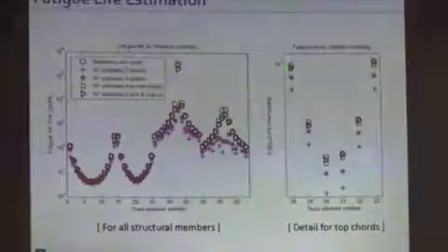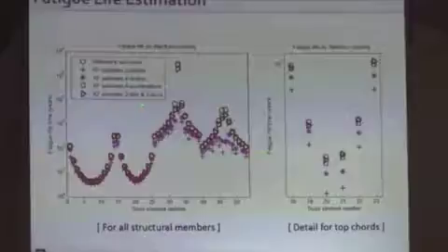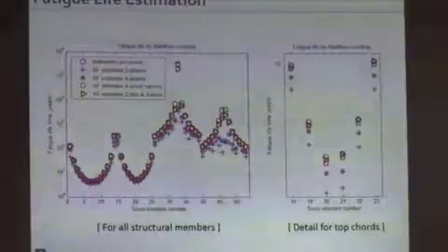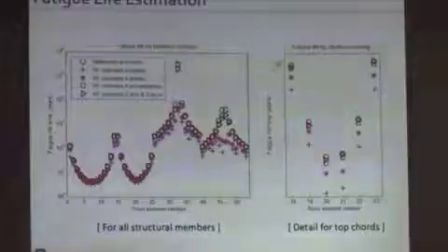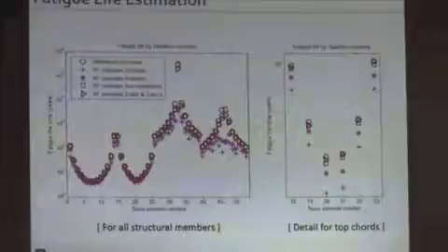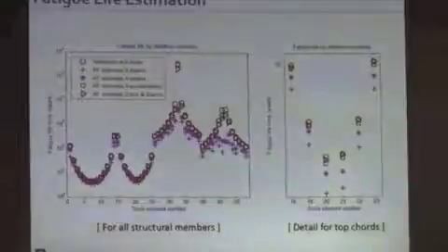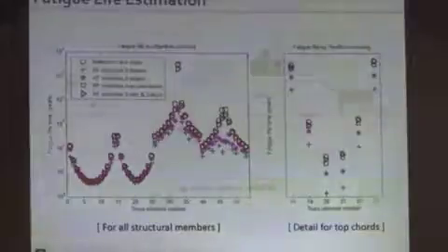So the black circle is the exact result. And so the Kalman filter estimates using the multimetric approach gives our best results, but the 4 accelerations don't do too badly. And why is that? That's because at the higher frequencies, that's where a lot of the fatigue damage goes on, not necessarily at the lower frequency responses. So just 2 strain gauges really underestimates the fatigue life, and even with 4 strain gauges, because it doesn't capture that high frequency, it just doesn't do a very good job.